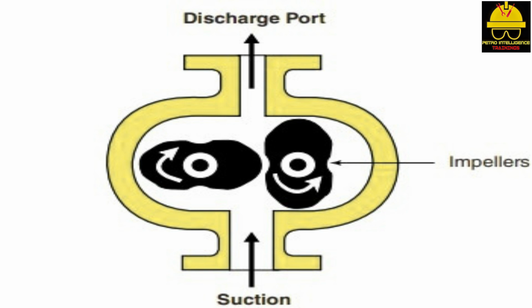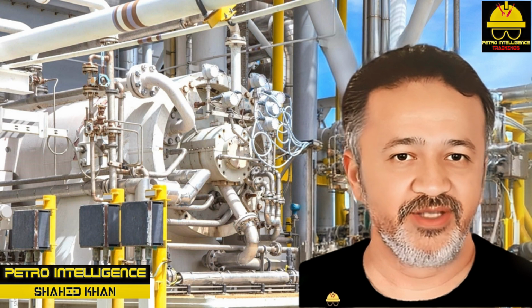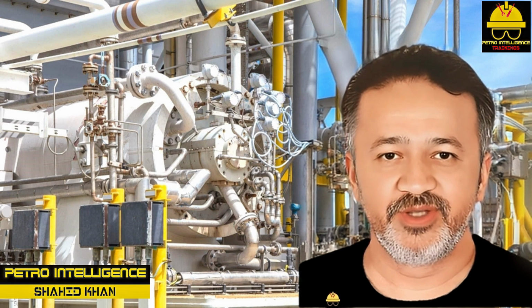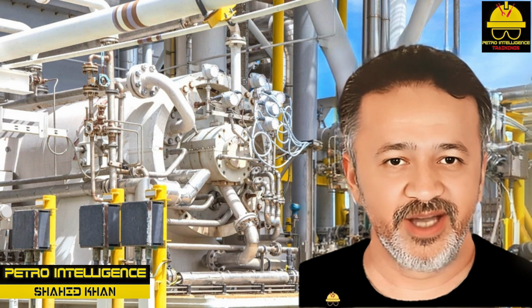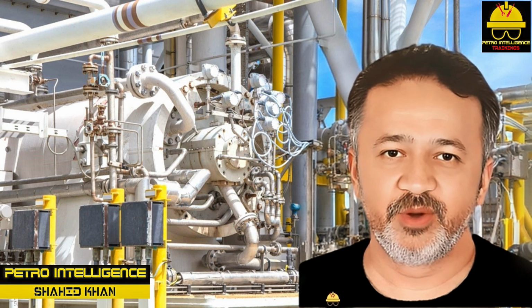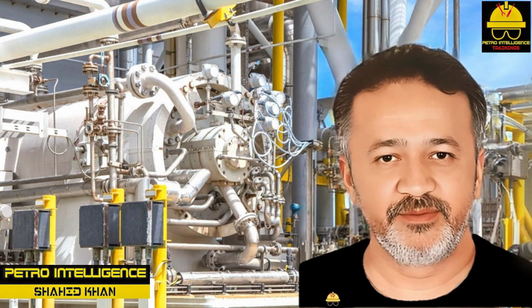Lobe compressors can be used in wet and dry gas service. The rotation of the lobes may be up or down, that is, the discharge port can be at the top or at the bottom of the unit. In dry service, the upward rotation is preferred. In wet service, the downward rotation is recommended so any condensed liquids can escape. Lobe compressors can be used as compressors or vacuum pumps.